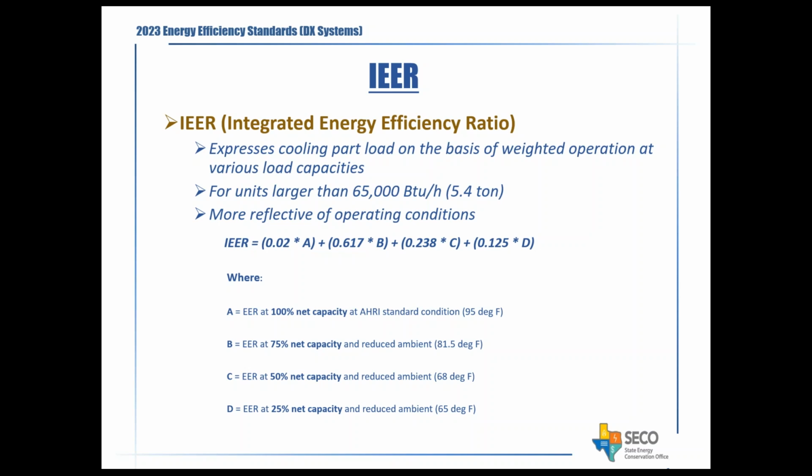What is IEER? The concept is pretty much the same as SEER, but it has more weighted averaging. So IEER will be calculated at different load conditions, and that's the formula for it. If you're interested in that, you will see that they calculate the EER of the unit at peak, at 95, at 81, at 68, and 65, and they've given some weighted averages to those to come up with the IEER number.